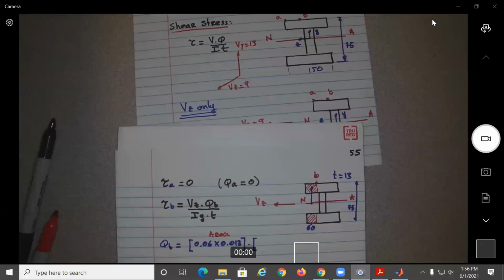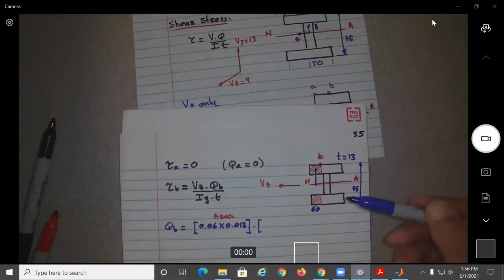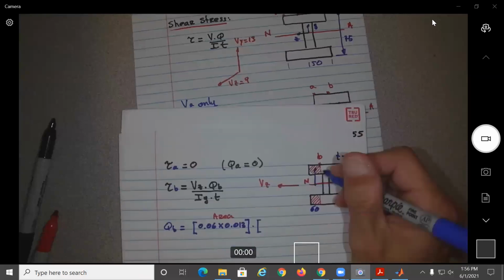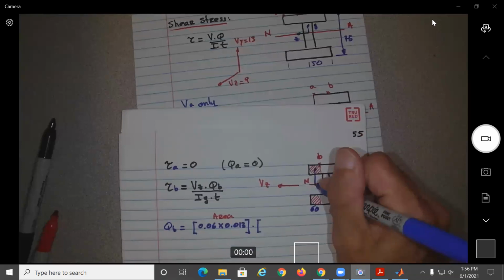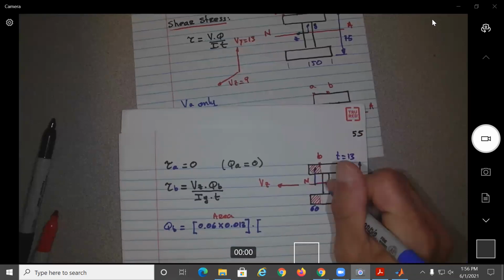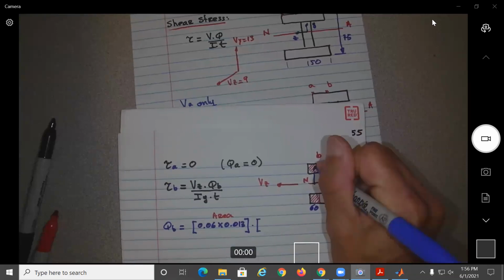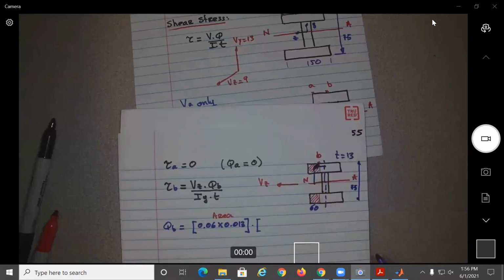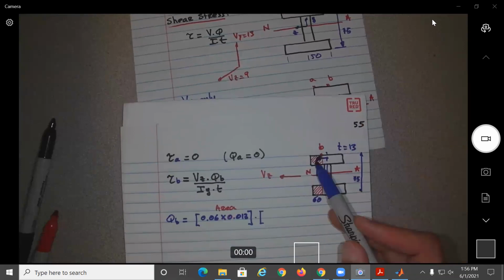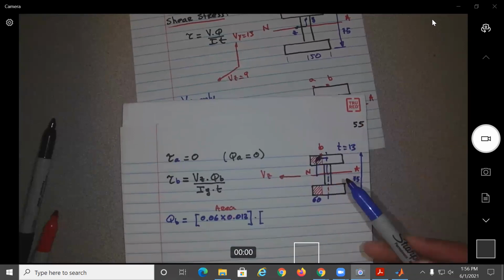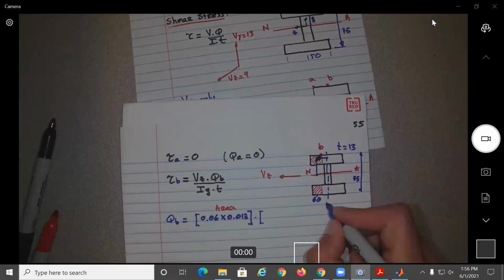What is the mistake that I've done? This is bending in the Z direction. So really the distance we should be looking at is not this one, but this one here, no? That distance here, 31, would be for looking at the Vy. So we're looking at that distance, from the center to there. So that will be 75. I think that was 150.